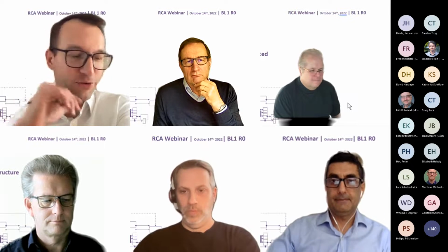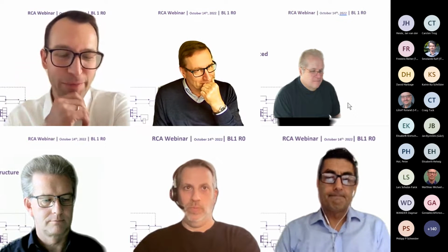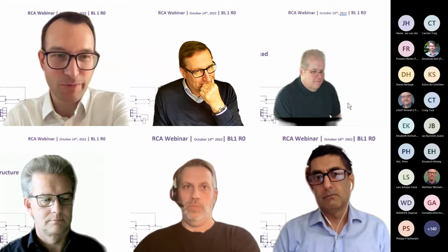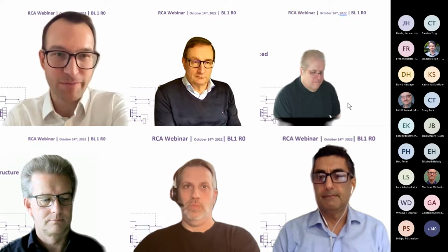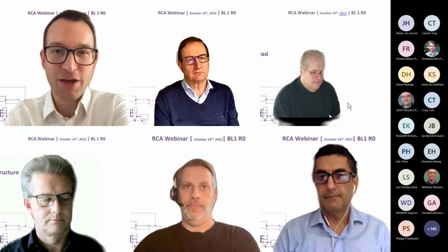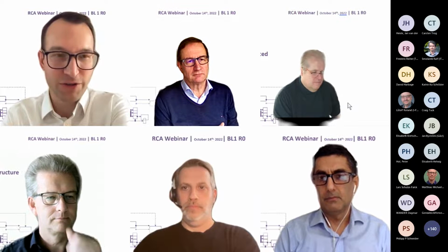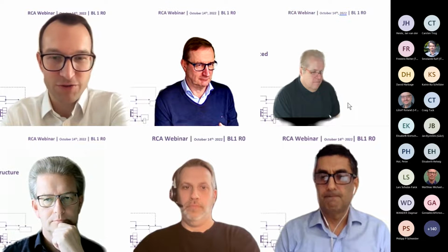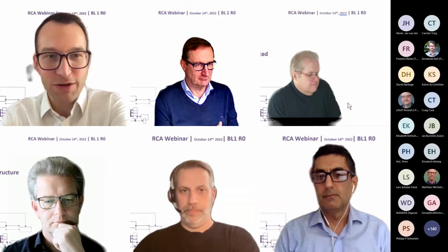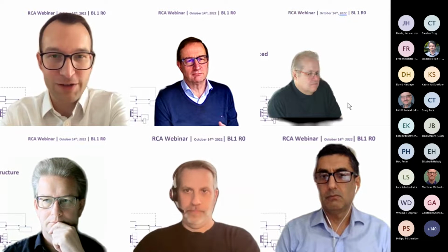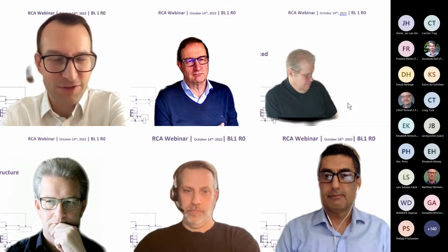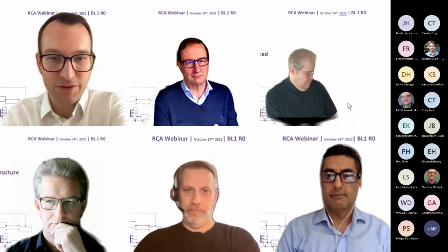Thank you. Michelle, I'd also like to add one thing to that. To help this migration, what Stefan said, you can already invest today in Ulinx standards. So buying your object controllers and fitting them with Ulinx interfaces and connecting them to your proprietary interlocking for a new project, that already helps a lot because most of the cost is normally in the field installations. And when you have that, and when you have ETCS on your vehicles, you have basically the two big migration steps that you can do now already. And then you can in the future upgrade your trackside centralized system, but not re-signaling your whole line again, using, for example, all the point machine interfaces and so on, axle counter interfaces that you already installed, and then just changing out the installed trackside central system.